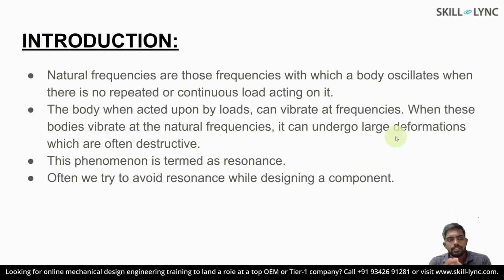So, frequency analysis. Any material vibrates at its own natural frequency even when it's at rest. Before we use any part in an assembly, we tend to study the frequency at which it naturally vibrates, to make sure that the operating range of the model doesn't fall near this frequency. This is to make sure that the amplitude of vibration of the model and the assembly doesn't multiply to produce a displacement large enough to disturb the assembly.